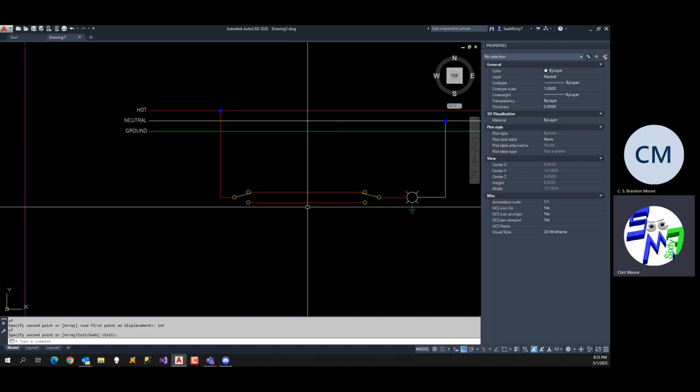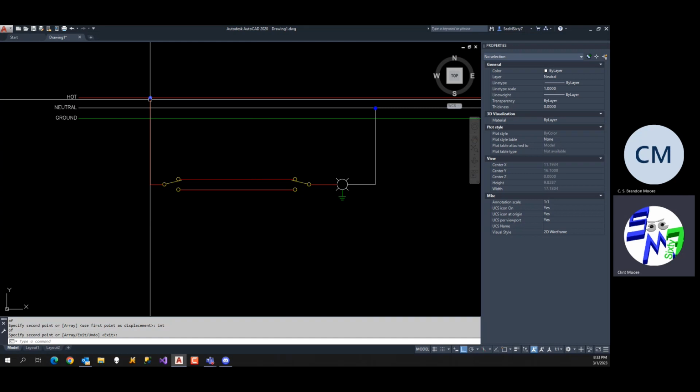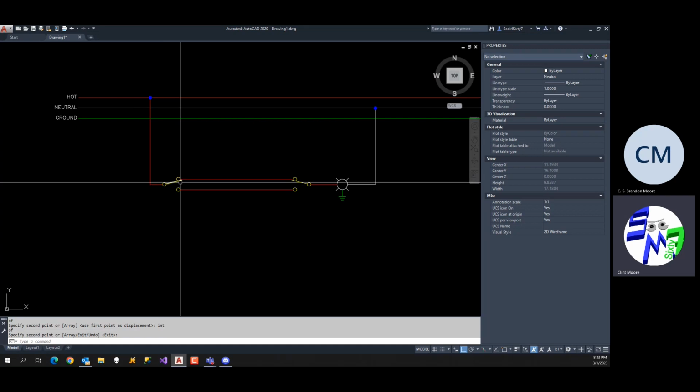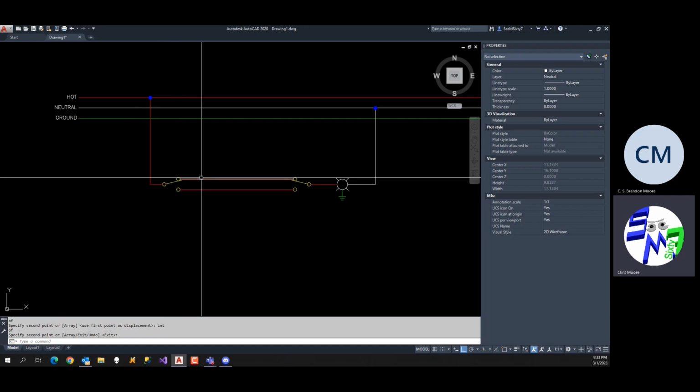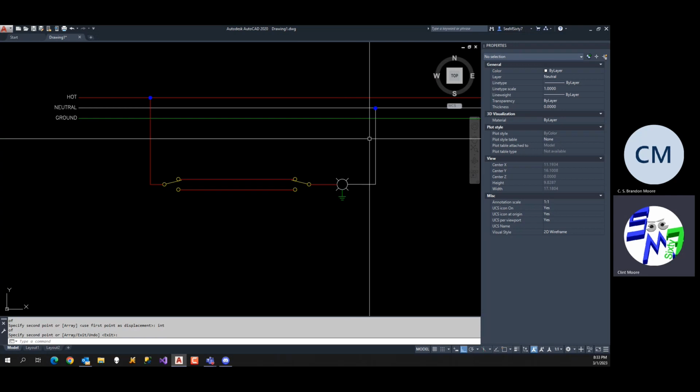All right. So the way this works is if you want the light to come on, it has to be able to complete this circuit. Power comes down through this wire here. It's 120 volts. Comes through this switch, goes up this way because this is the way that's connected. It travels across this traveler, comes down this side of the switch because it's connected, hits the light, goes into the little resistance of the light, which is that filament, and then it starts glowing and it comes across here.